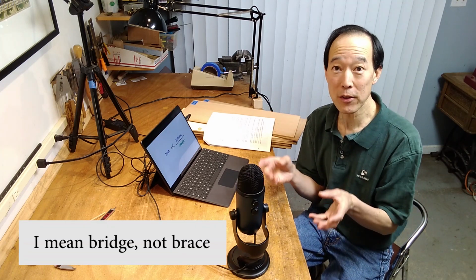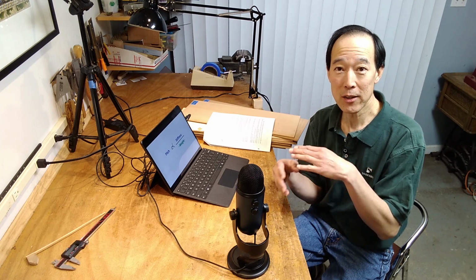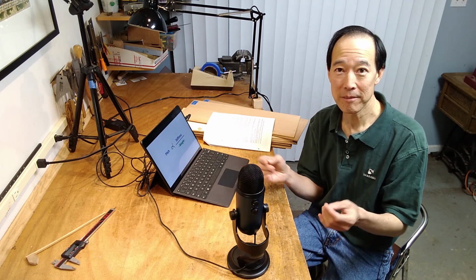But there are exceptions to this, of course. Consider when you add a brace, which adds stiffness, but it also adds a huge amount of weight. And so that could be a factor in determining pitch. Now, this is just for pitch, but of course weight will have severe consequences on volume and sustain, so just keep that in mind.